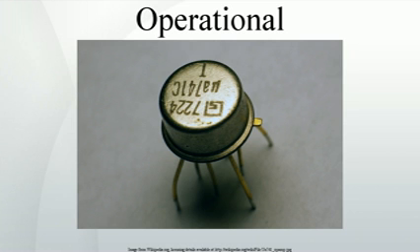When an op-amp operates in linear, that is, not saturated, mode, the difference in voltage between the non-inverting, plus pin and the inverting, minus pin is negligibly small, and the input impedance between plus and minus pins is much larger than other resistances in the circuit. The input signal Vin appears at both plus and minus pins, resulting in a current I through RG equal to Vin/RG. Since Kirchhoff's current law states that the same current must leave a node as enter it, and since the impedance into the pin is near infinity, we can assume practically all of the same current I flows through RF, creating an output voltage. By combining terms, we determine the closed-loop gain ACL.